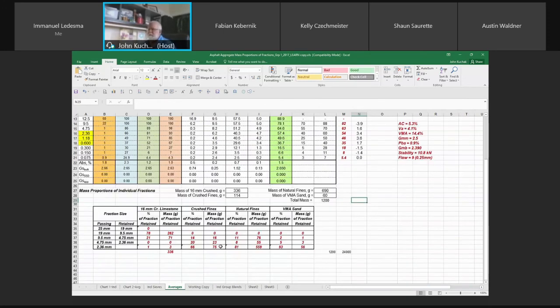So now when you're in B109, we'd need 4 samples. Typically, you should do 3 briquettes for every AC content plus 1 for maximum theoretical specific gravity. But we've cut down our lab because of time in car C and in B109, because we compact in car C, because we have the fume hoods and everything else.